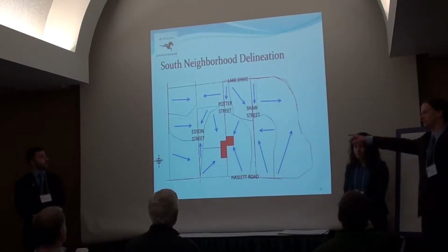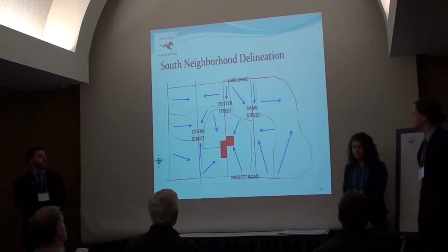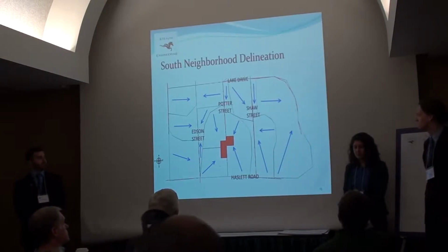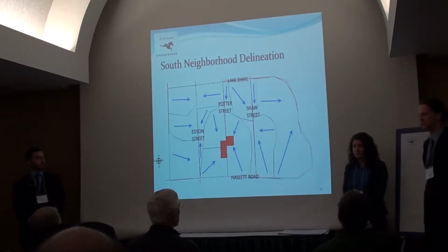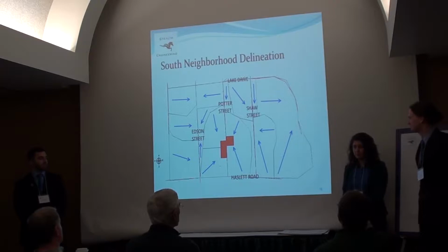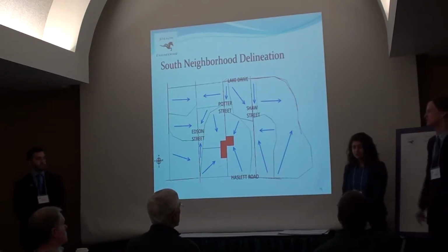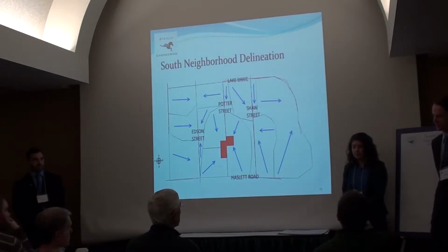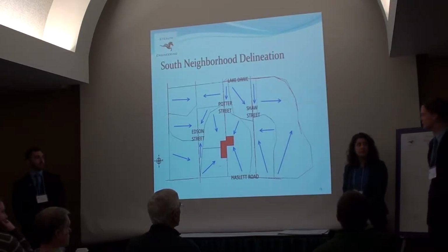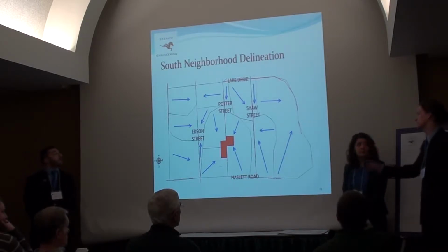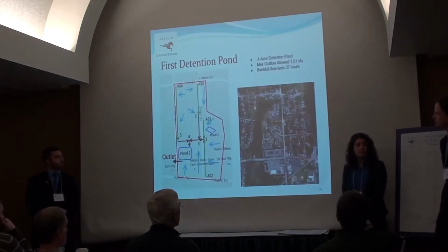This elevation of 850 feet, it was first considered to put a standard piping system throughout the whole neighborhood, conjoined together and brought it all to one off-site detention pond. However, with this elevation at 850 and regulations of 3 feet underneath the ground for the pipe, this would give very little elevation change to allow a detention pond to be placed off-site with this water running through it.